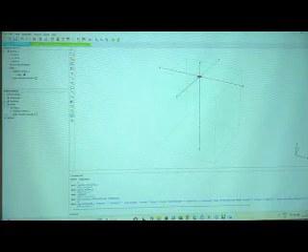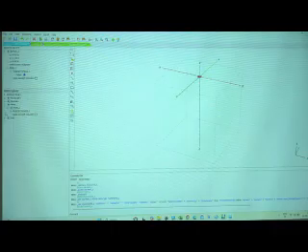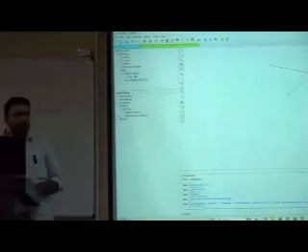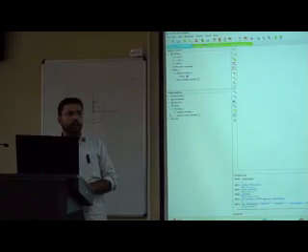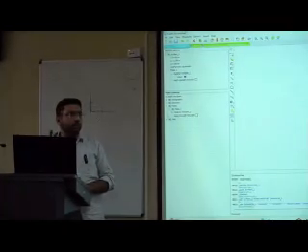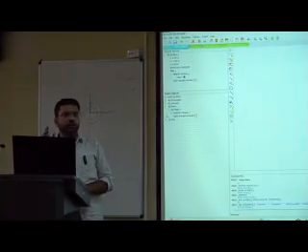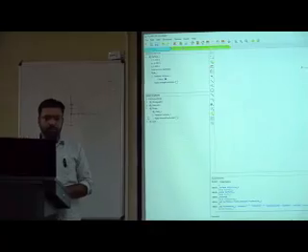In Plaxis, there are two options for piles. One, you can go for the volume pile. Another is the embedded beams. In my Plaxis, the volume pile part is not working, so I am going for the embedded beams.